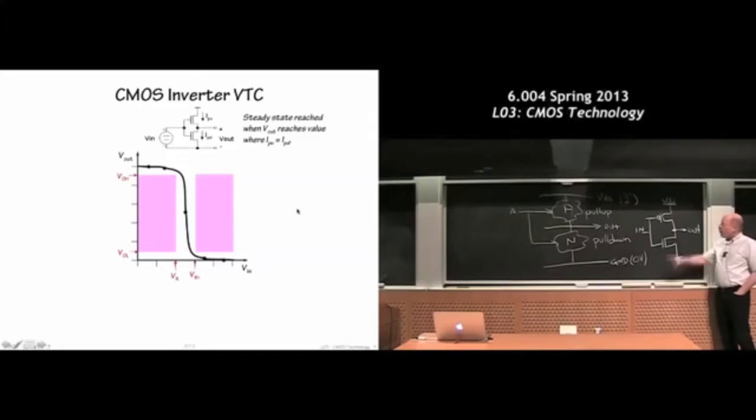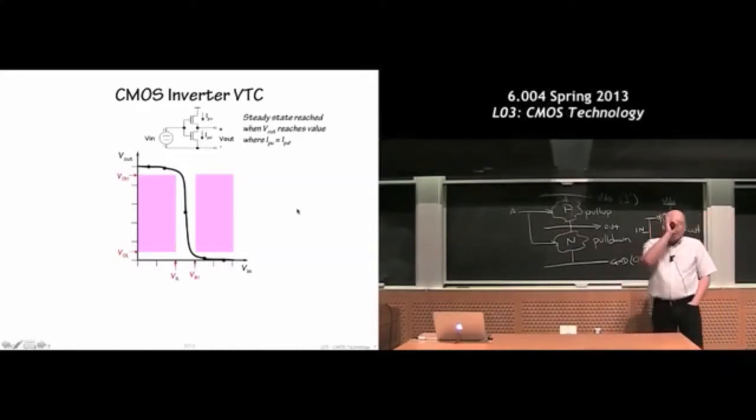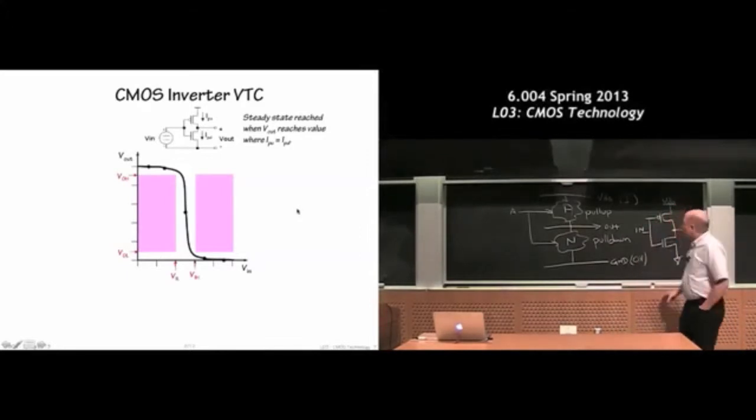That device has, first of all, notice the schematic symbols. This is an NFET. And this, the same picture, except with a little bubble on the input to remind us that it's inverting. In almost all logic diagrams, those little bubbles mean invert. So this means that this switch is conducting when the voltage is high. This switch is conducting when the gate voltage is low. So how does this device work?